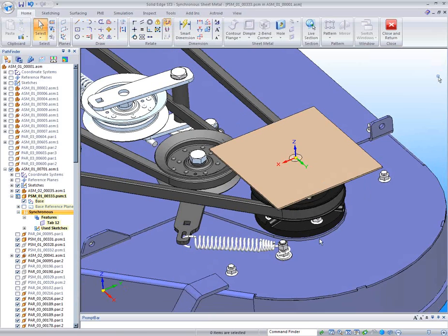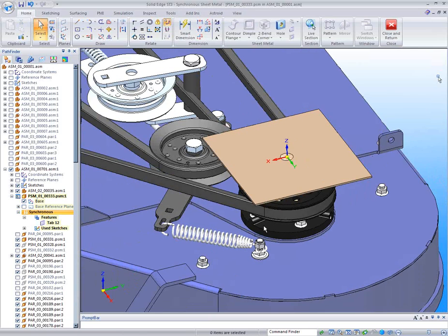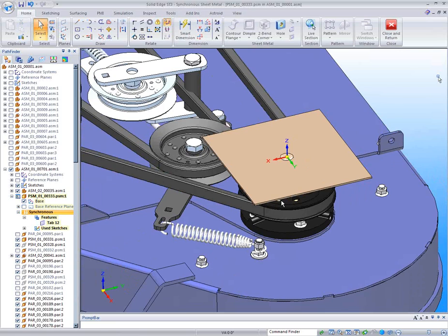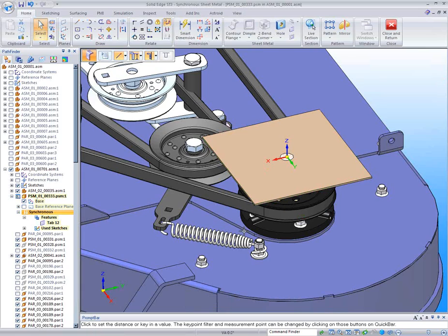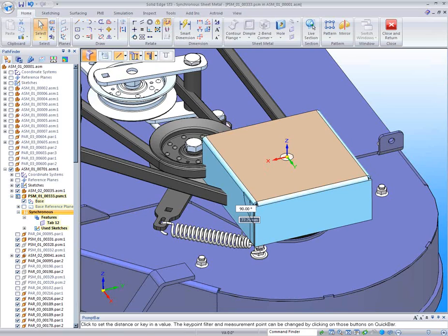Now, I want to come down with some sides on this piece, and I'm going to hit the space bar, and the space bar is pretty much like the control. It allows me to pick multiple sides, so I'm going to come down 3 sides at once. Now notice we're not even using the word flange, because Solid Edge simply knows if I pick that side and I start to bring it down, there's only one thing that thing can do, and that is come down as a flange. So again, the time-saving commands, I'm not going through the ribbon bar.